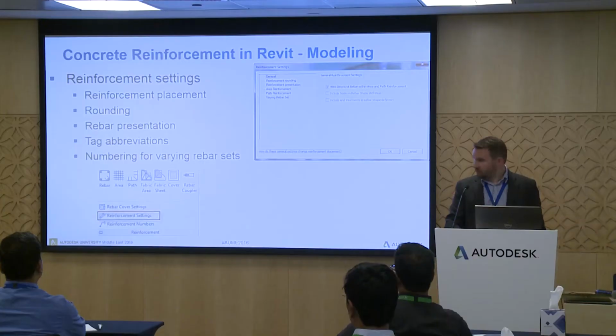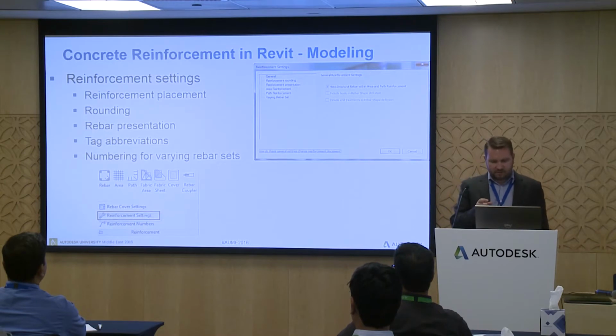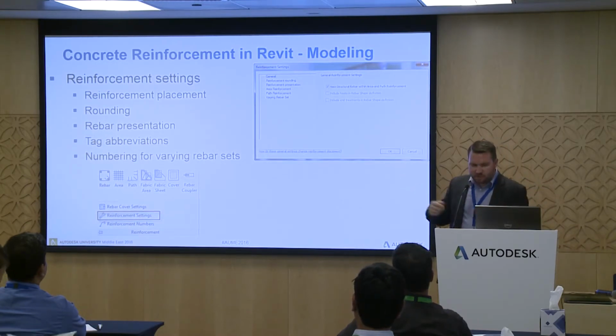We will start at the beginning of this session. So even if you have never configured or looked at reinforcements, you will know where to start. At first you will look at general settings. In general settings, you can of course choose whether the reinforcement is hosted by Revit or not.